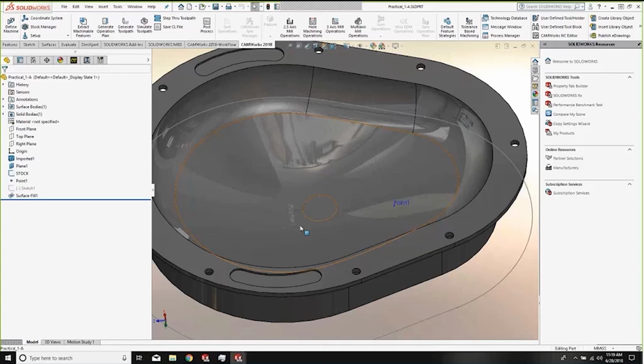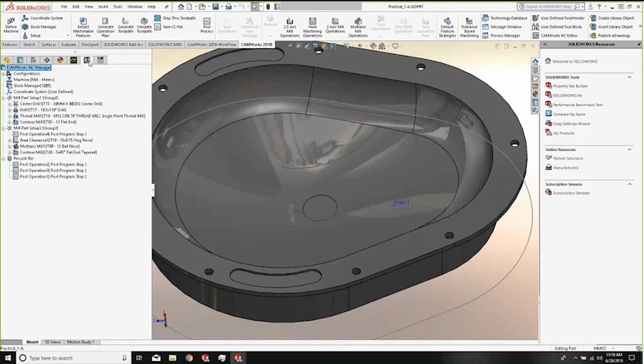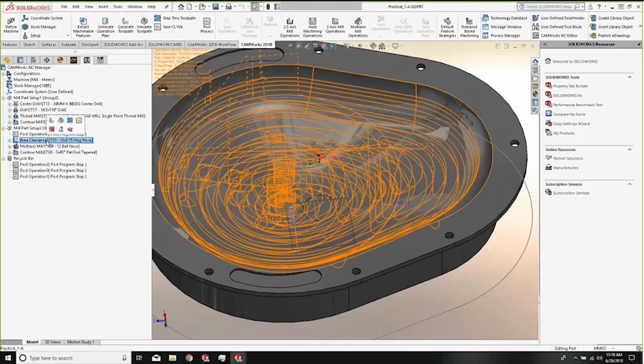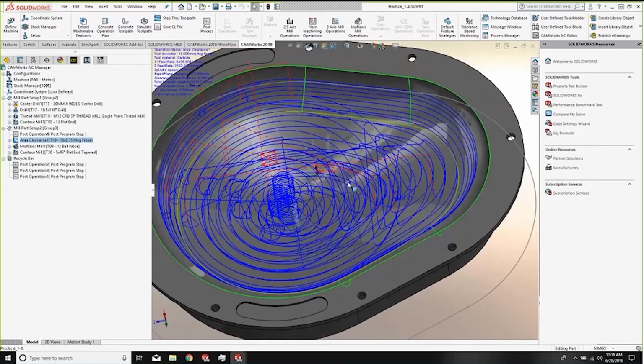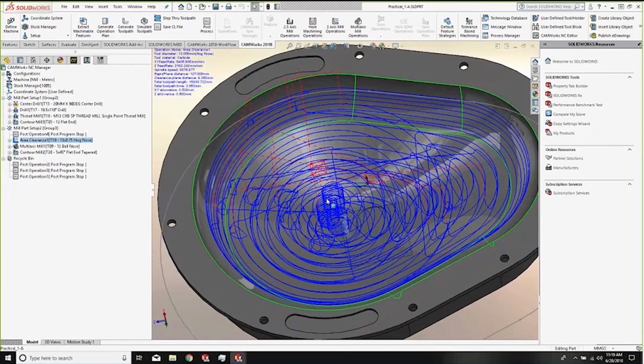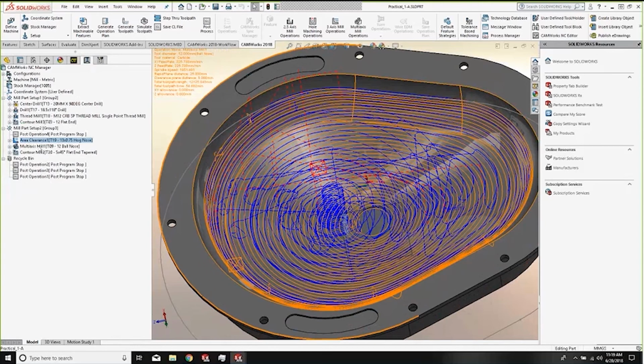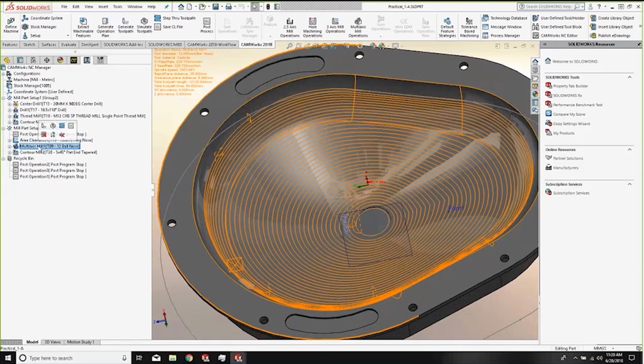So when it comes to surface machining, retracts are really our biggest nightmare, as I like to call them. Sometimes we can deal with them, sometimes we can't. Sometimes we can get rid of them, and sometimes we can't, depending on the surface. But this type of geometry, I can still go in and do the area roughing, rough all that material out of there. And then, since I have the full simultaneous 3-axis options available to me within CAMWorks, I can come in here.